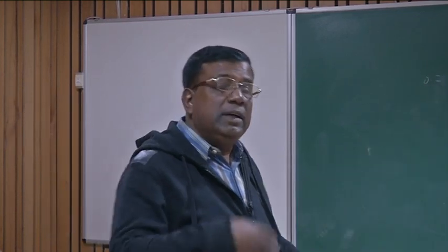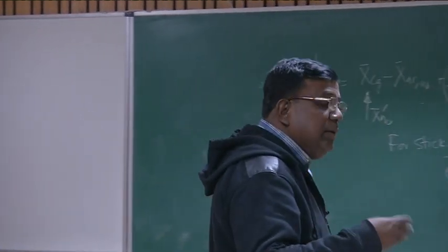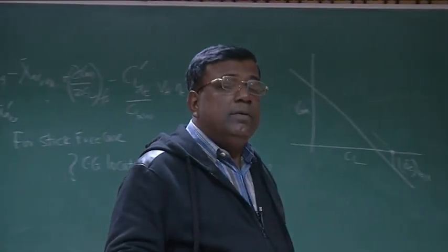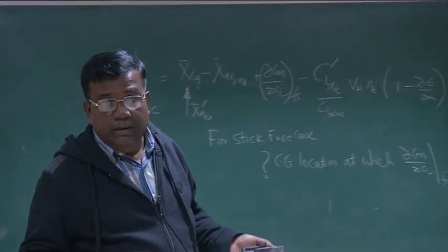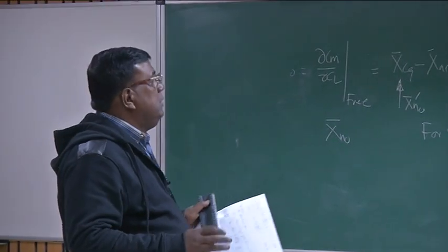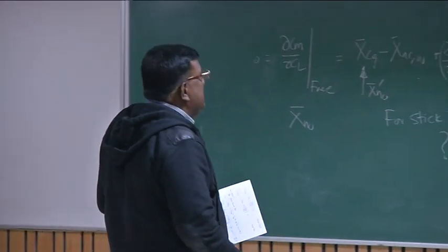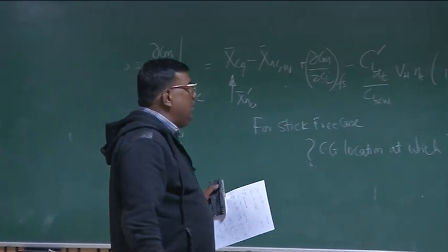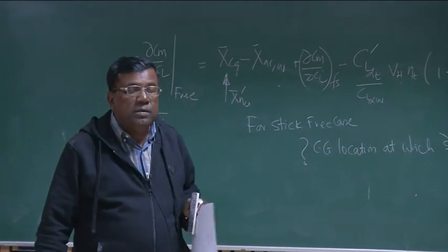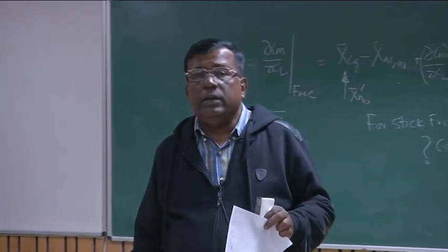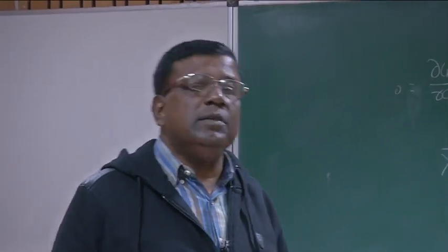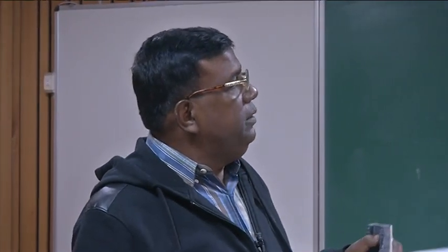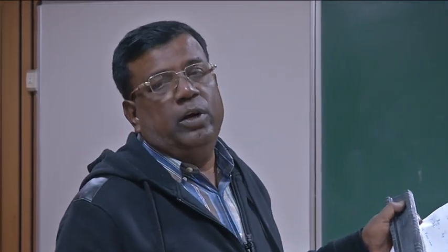That's the concept, to develop a mathematical model to relate stick force with the flying condition, CL or speed, right? So please keep this at the back of your mind, and this concept of stick-free neutral point is only true for reversible control, but unfortunately most airplanes now have gone into irreversible control. Just for completion, I'll perhaps be taking one more lecture on this.